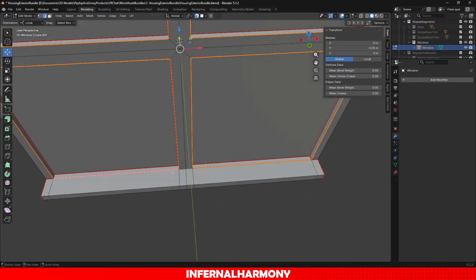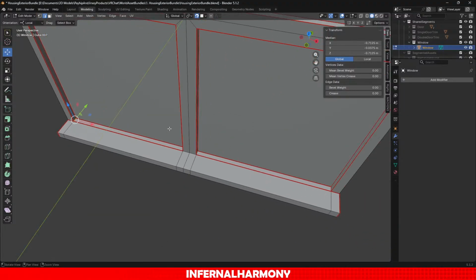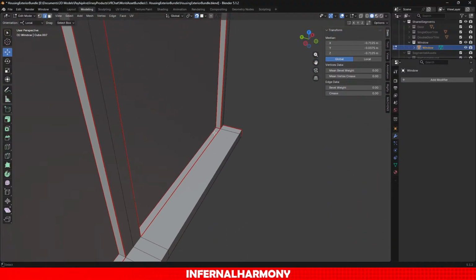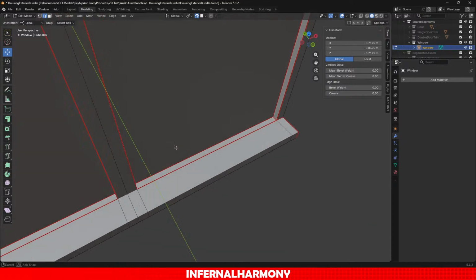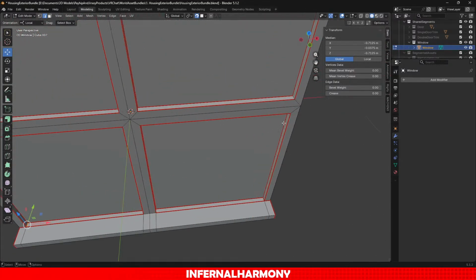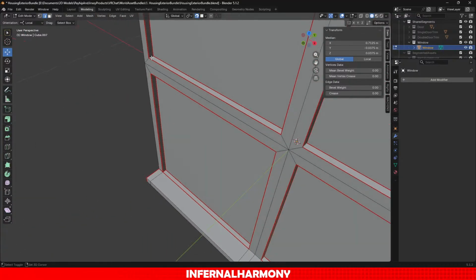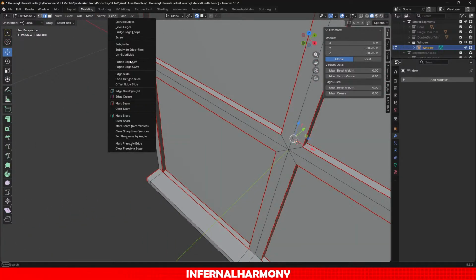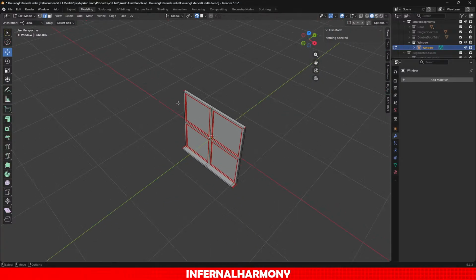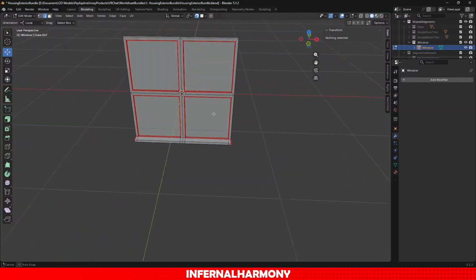That just seems like it's what would be the cleanest in my personal opinion. Then I can clear these edges, or actually I can keep those two, because that way those roll out cleanly. Then I will once again select these. Edges mark seam. That flattens that out.